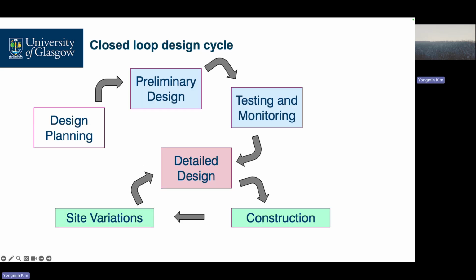So, design planning. Okay, sites, construction projects, how many buildings? Now we have east to west, how many stories? Certainly the E1 building is higher than this. This is design planning. Then we do preliminary design. How many piles? How long are they? Then we do pile load tests to verify your design.